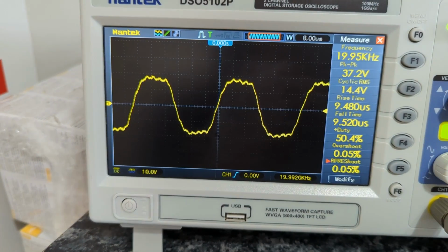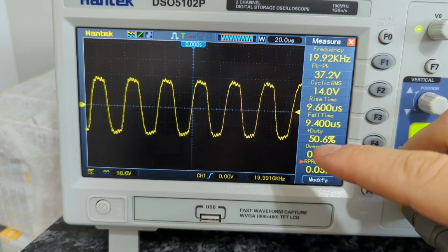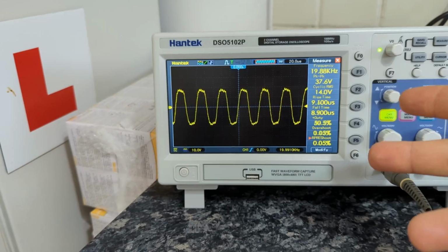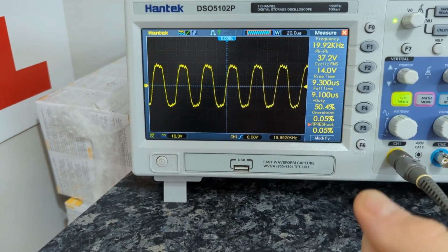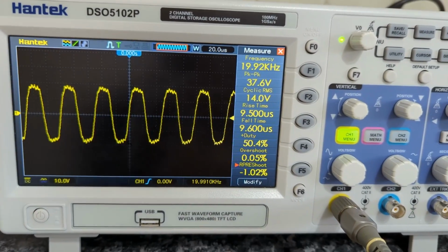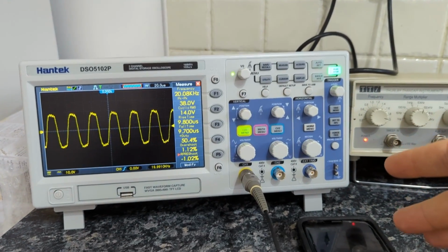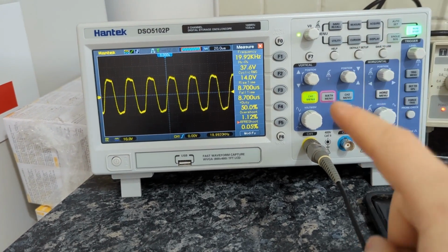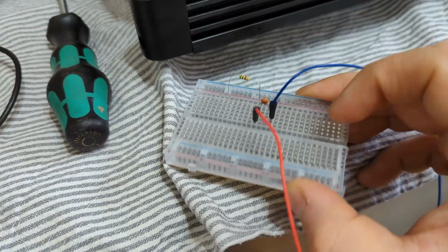And if you look at it, yeah, it looks horrible. But this is just because you have that 300 kilohertz square sine wave riding on top of this wave, and it's not correct, so you cannot really measure it. The way to do it is to have a low pass filter and chop off everything above like 20 kilohertz. So some scopes have that function. This one has, but it has a low pass only at 800 kilohertz, so it doesn't affect that because it's way before that.